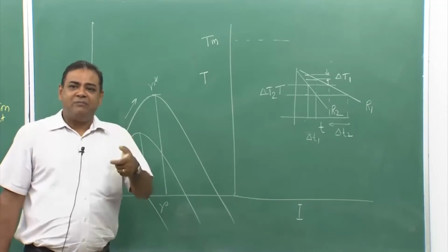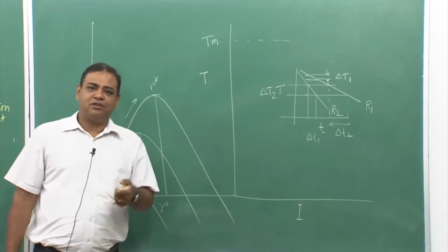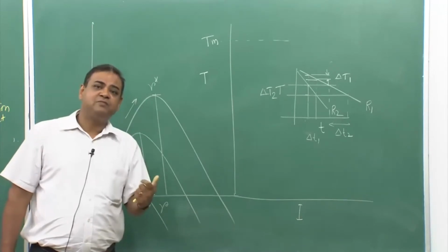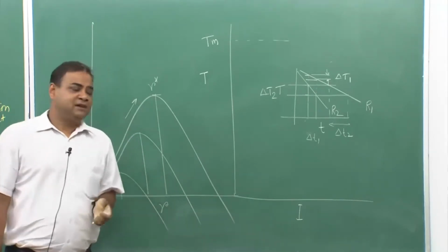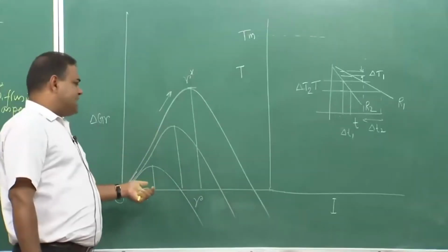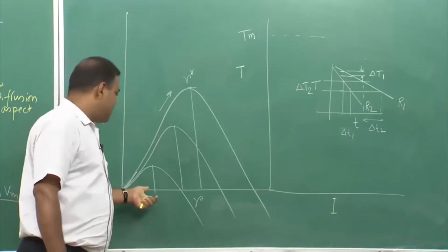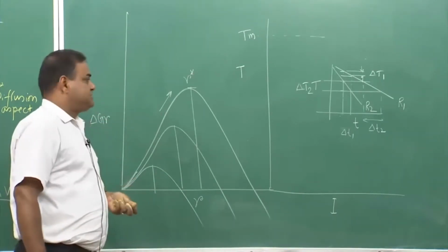That means, I am reducing the critical radius because of higher undercooling, and that is because of higher cooling rate. So, this gives a little idea that yes, if we go for a higher cooling rate, higher undercooling, I would get very finer structures.